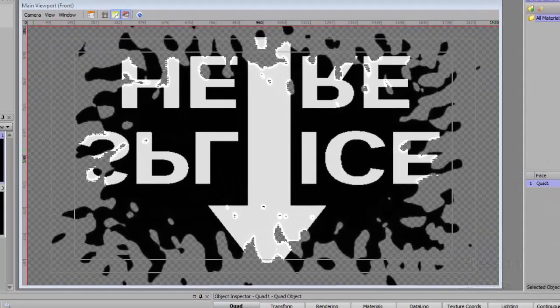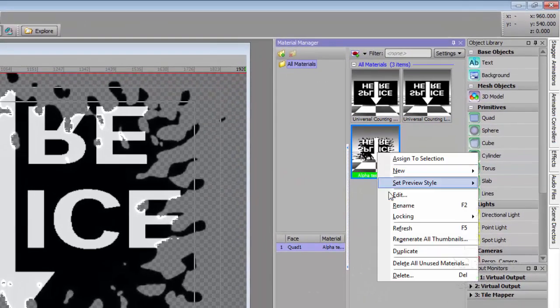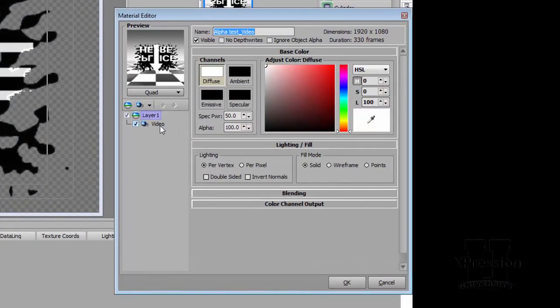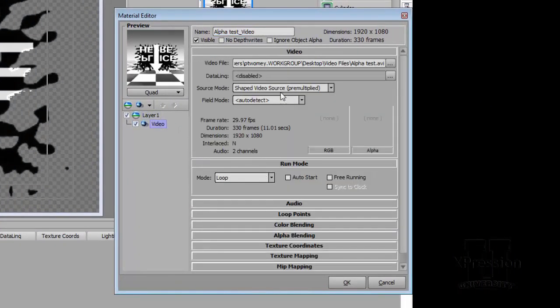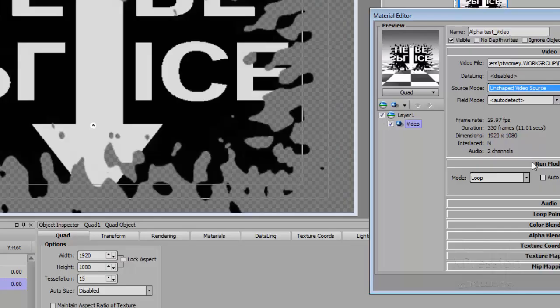And I want you to notice a couple things. First off, it's not playing when I added it, and that might be okay. The other thing I want you to notice, it's kind of ratty on the edges, and that's kind of on purpose here. So I'm going to go back to my material. I'm going to right click on it, choose edit. I'm going to choose the video. Then I'm going to do two things. First off, see where it says source mode? I'm going to change that source to unshaped video, and you can see that cleans it up considerably.